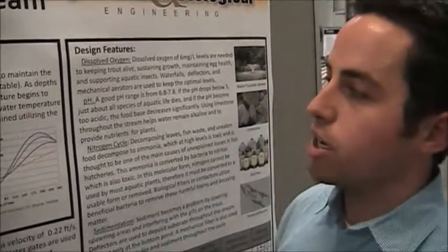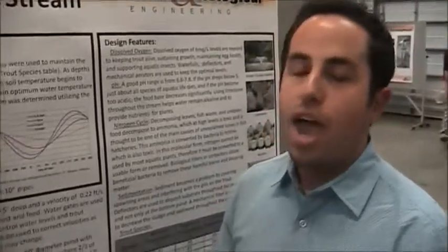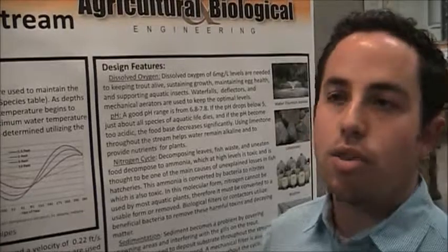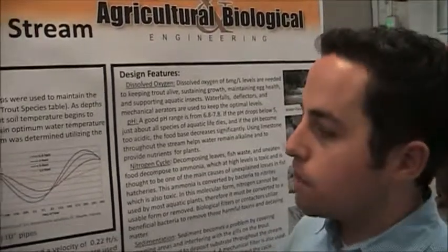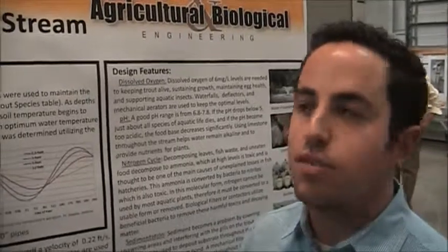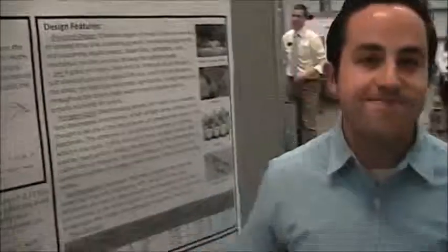And so what we are doing in our design is we're taking the water we are pumping in that stream and we are pumping it at depths of 20 feet. That way, as we pump that water, it will have the necessary heat loss to keep that 55 degrees in the hot summer months and also in the cold winter months.